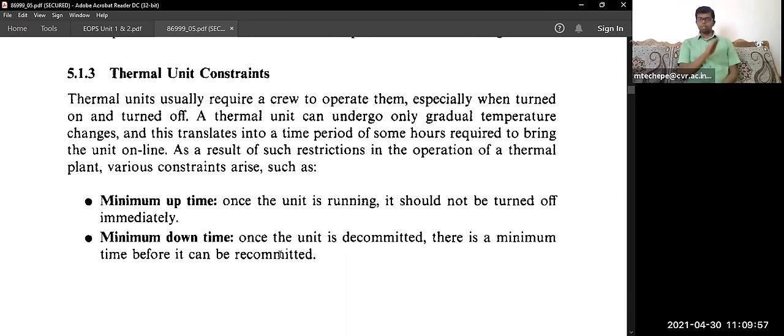Say, for example, from 9 o'clock to 2 p.m. they may plan to operate. If they want to turn it off at 2 p.m., from 1 o'clock itself they may reduce the boiler temperature, then the furnace temperature, and slowly from 1:30 onwards they will turn it off. It will take 1 hour to make it turn off.